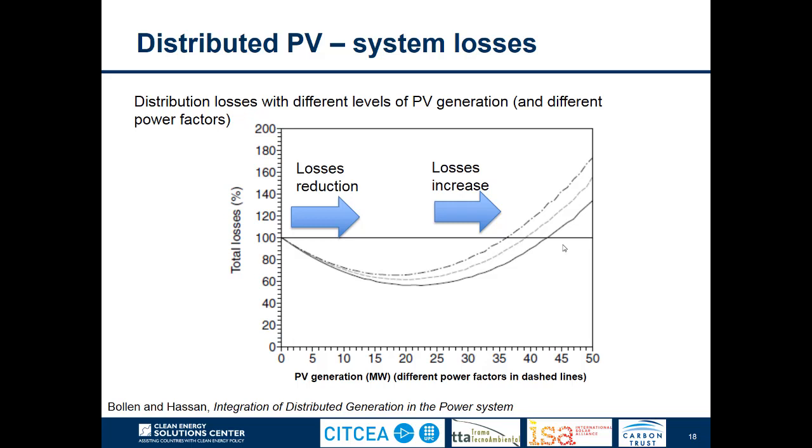At the end, it is not only important to have a given power injection from the photovoltaics. Also, depending on the reactive power we are exchanging between the photovoltaic plant and the system, we can achieve different losses. We discussed in other modules that the solar inverters can also control the reactive power they are exchanging with the grid.